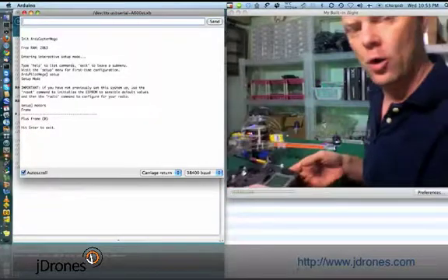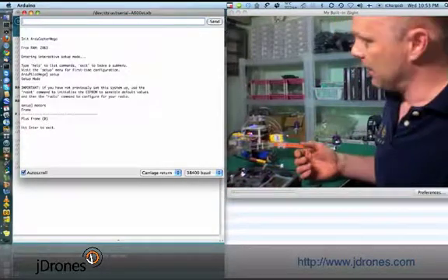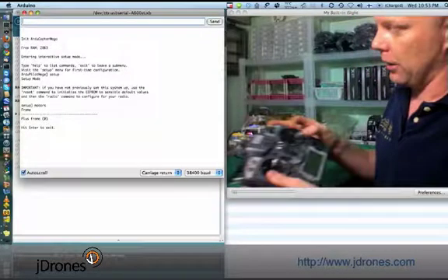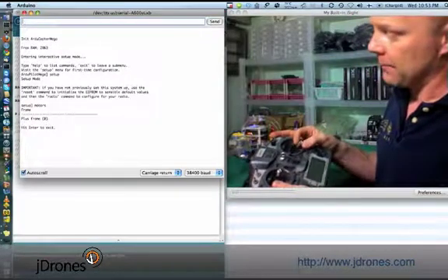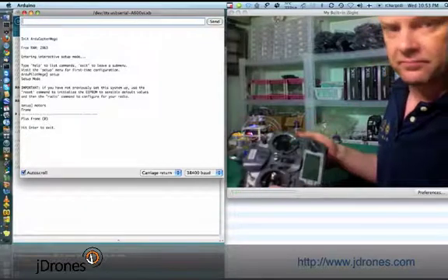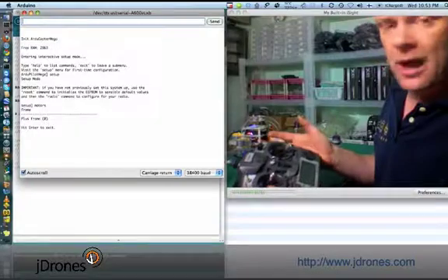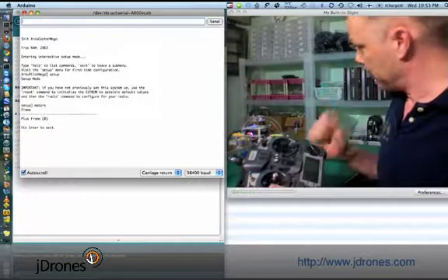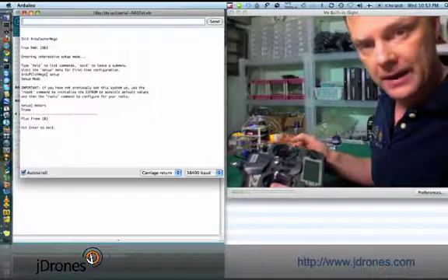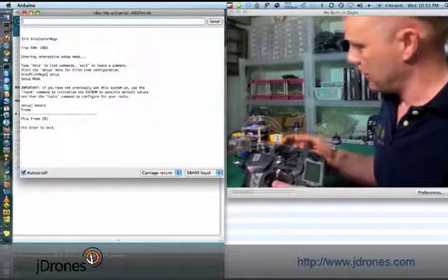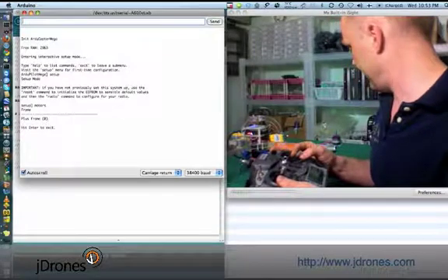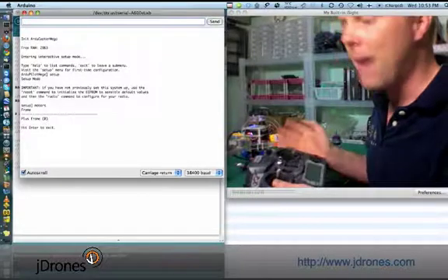And there was the one long beep, saying that the ESCs are now calibrated. And if you now push some throttle, all the motors will start spinning. This is also the time when you can test and check whether all the motors are spinning at the right speed. You can hear it, you can see it, that they are spinning at about the same speed.